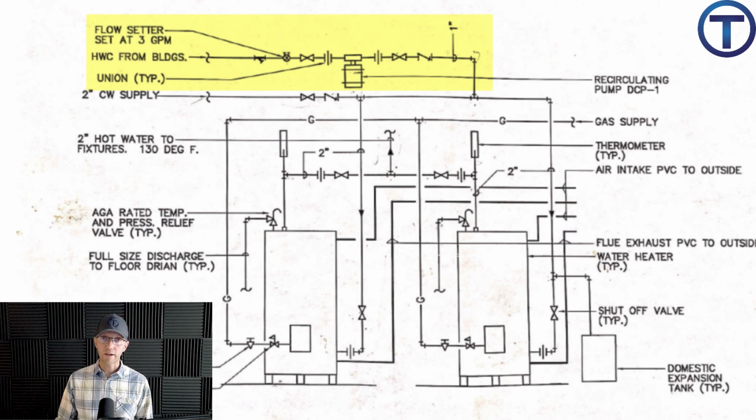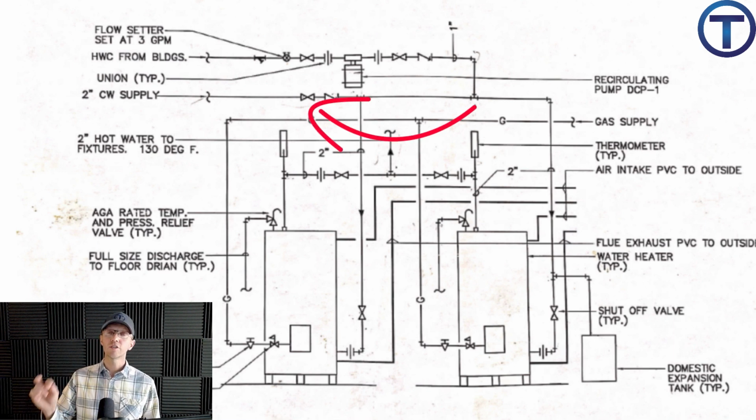There's a check valve so that water can't be feeding backwards into that recirculation line from the cold. And that line does connect into our cold side somewhere. As we look at design, probably better to have that connecting before the T that branches to both of the water heaters. So once again, it's pushing evenly through both of them.